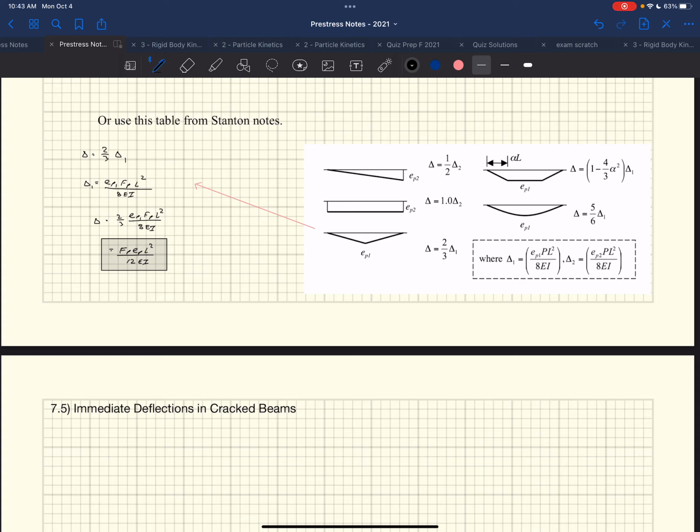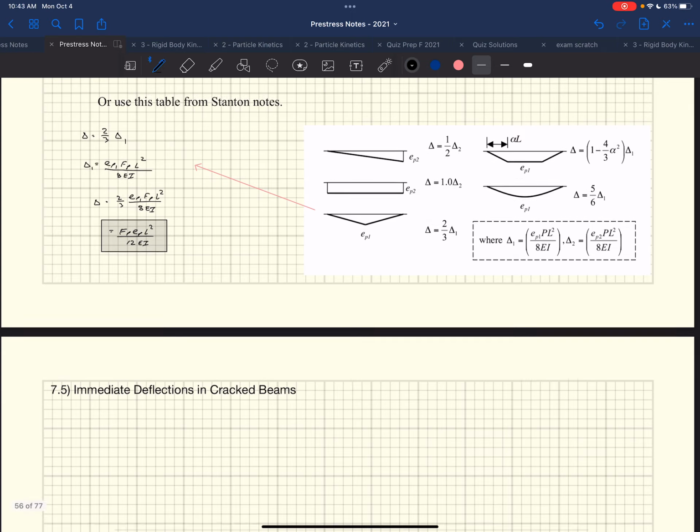And so usually we design them as being parabolic. That'd be a great question for Kyle, on what they do when they have that thing going through. Like, what assumed shape do you have? Yeah, just the dead load of itself would make that cable take a certain shape. It's close to being quadratic, but it's not. I'm not sure what they do in the real world. If the computer program assumes a shape, what shape are they assuming? I'm assuming he's assuming a quadratic in this case. Yep. The math kind of looks that way. Okay.